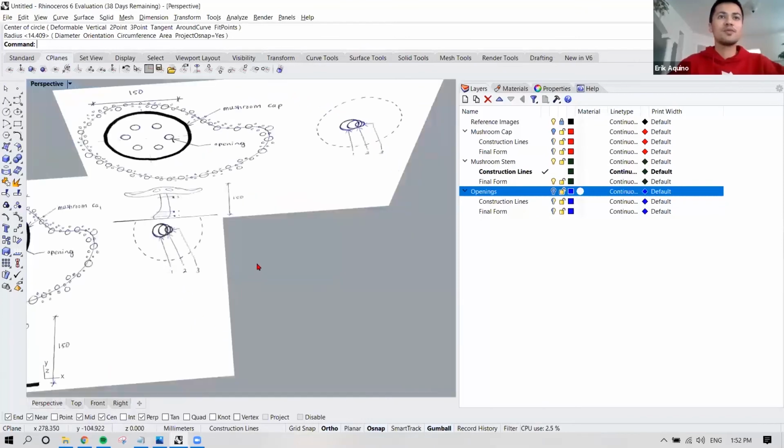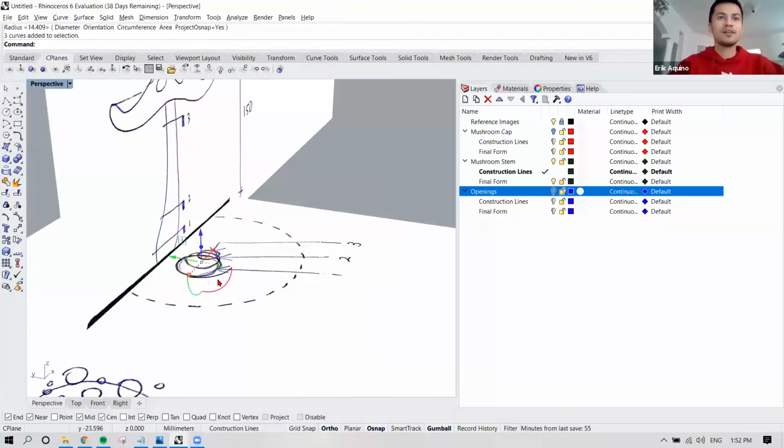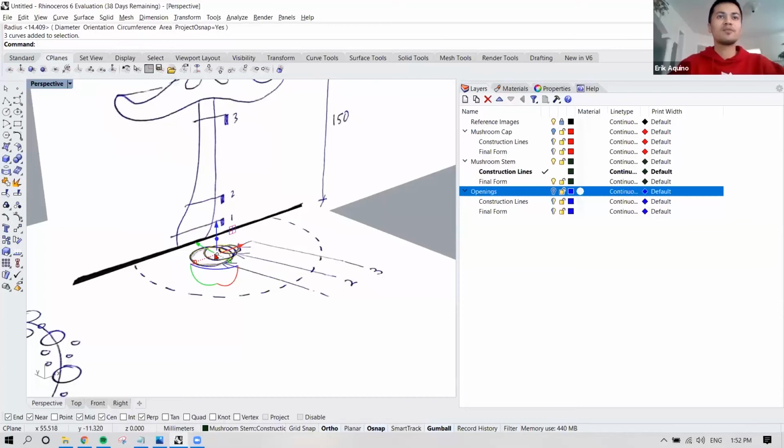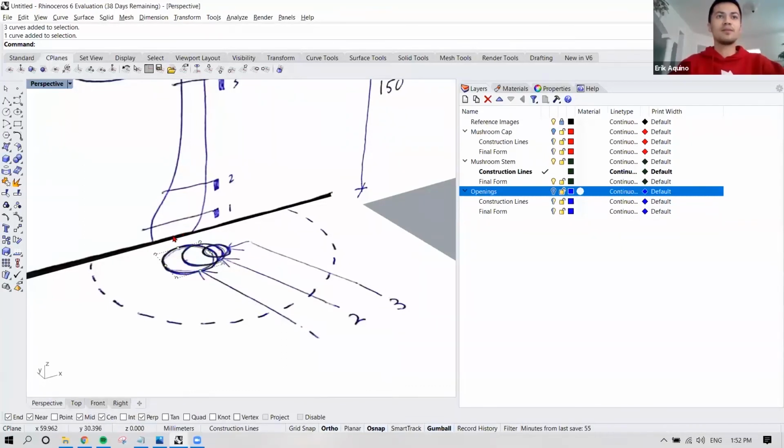As I've mentioned with the previous steps, our curves are going to be placed on the XY plane, and we have to move them up to their associated level. So for our level 1 curve, I'm going to make a copy, so that we have at least a profile to start off with on the base. So I'm going to copy it, and again, hit in place so that you make a duplicate right on top, so they're superimposed.